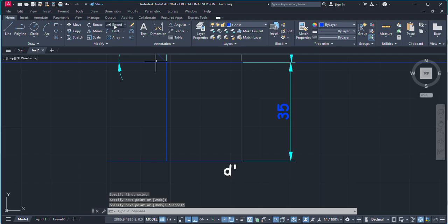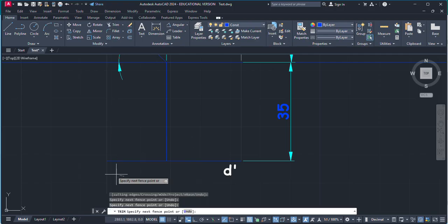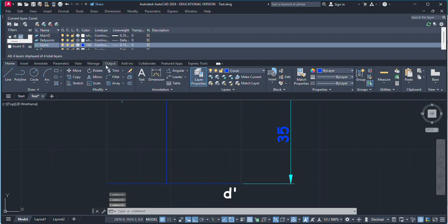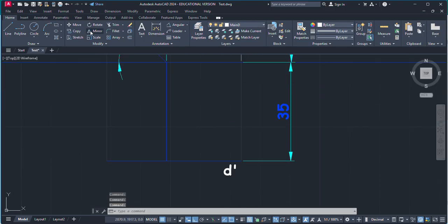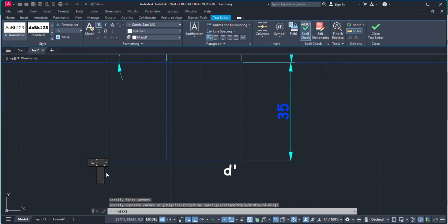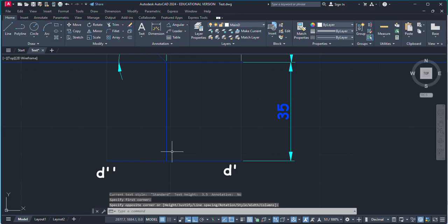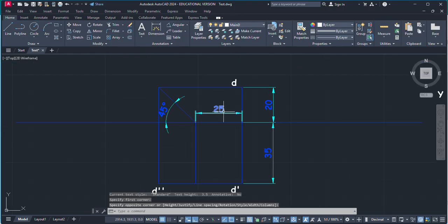So this point of intersection is our side view, or our right side view, which is on LPP, left projection plane. Just name this thing D double dash. Okay, we need to highlight the points, so just use donut.